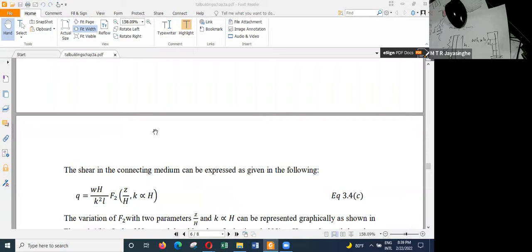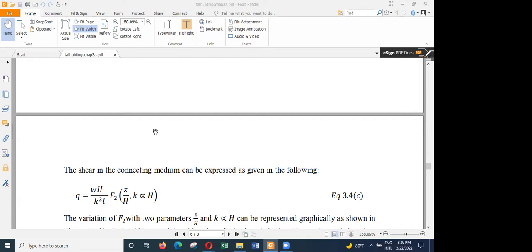And when every engineer is united and telling that the minimum thickness is 225, it becomes 225. 25 millimeters can make a huge difference, because that 25 will give enough space to insert the normal poker vibrators. Otherwise, even the poker vibrator cannot be inserted when you have 200, when you have thick, strong walls with a lot of bars. In a tall building, I will go for 300. This is a significantly tall building; I will not go for 200. The other question is: is it wrong to design shear walls floor by floor?